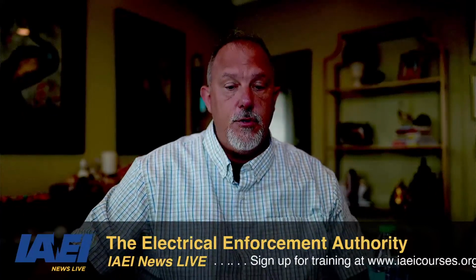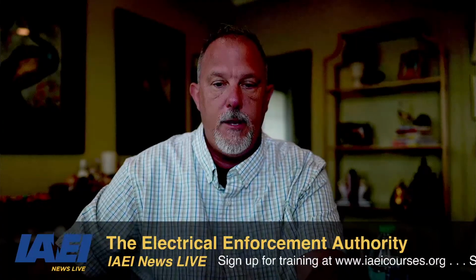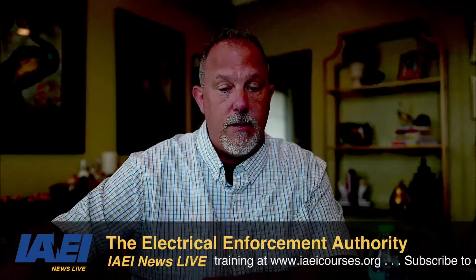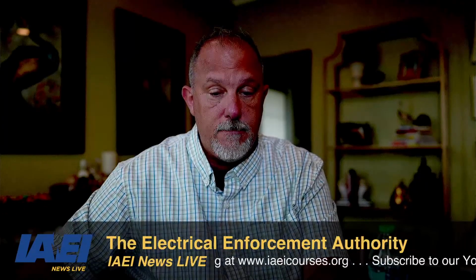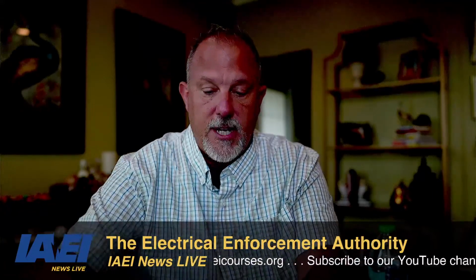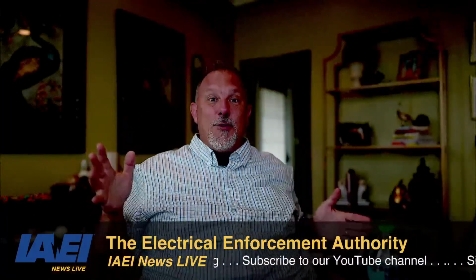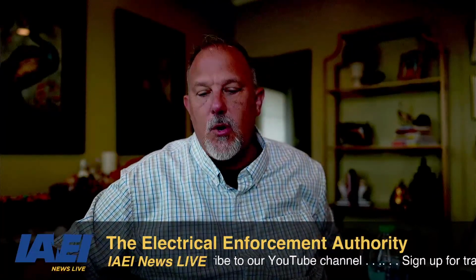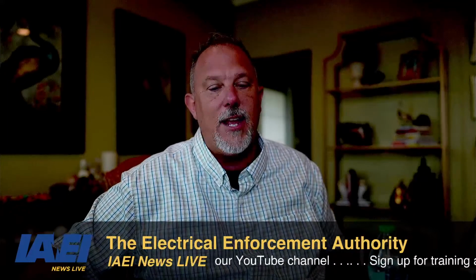This is your multiple PV string circuits. It says where an overcurrent device is used, and I'm going to say an overcurrent protective device is used to protect more than one set of parallel connected PV string circuits, the ampacity of each conductor protected by the overcurrent protective device, OCPD. Oh man, we can use the acronym. There, Dawn, that just opened up a whole nother world. I could just say OCPD.